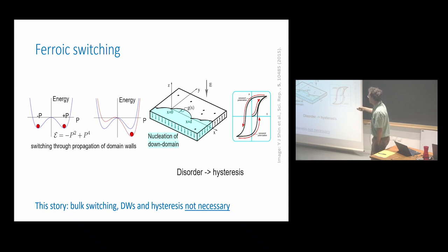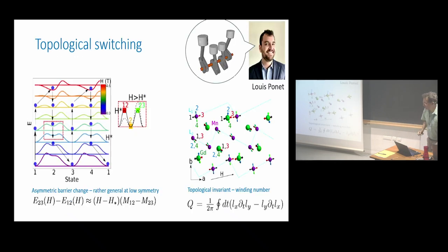The domain wall hits all kinds of disorder, dislocations, and impurities, and that leads to the hysteresis. The area of the hysteresis loop gives the energy required for the switching cycle, and that's the heating that we would like to avoid. I will discuss a material where it seems that such heating may be avoided.